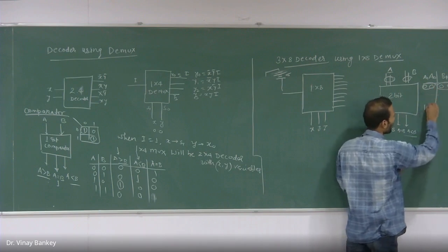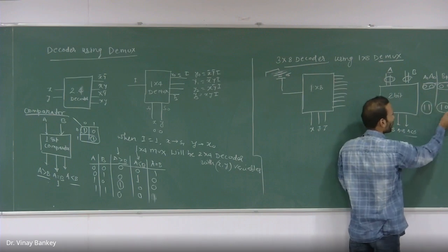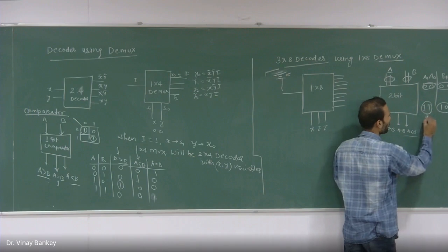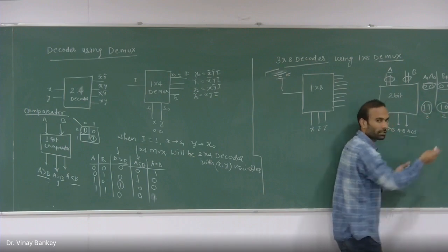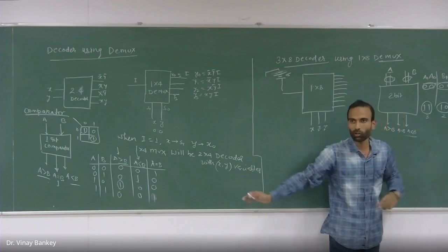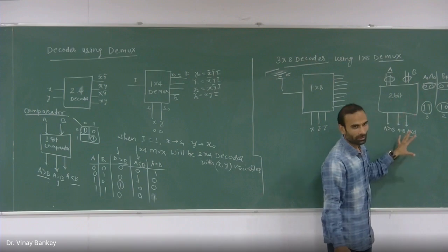Let's suppose here it is 1 1 and 1 0. So we'll compare this 1 1 with this 1 0. This 1 1 holds the weightage of 3 and this is 2, so A will be greater than B. Accordingly, you will fill in the truth table for these three outputs. In this way, you can design a 2-bit comparator.